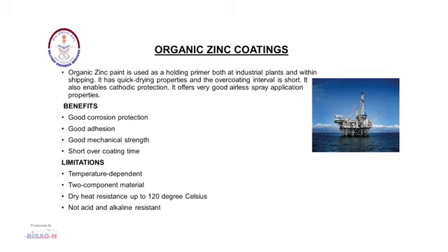Benefits: good corrosion protection, good adhesion, good mechanical strength, short overcoating time. But limitations are temperature dependent, two component material, dry heat resistant up to 120 degrees Celsius, and they are not acid and alkali resistant.